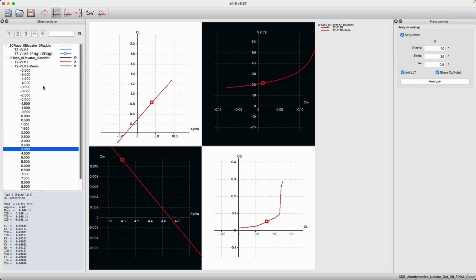And as you increase your angle of attack, the lift coefficient will increase, and because your drag is increasing, the horizontal speed will decrease, right? You can see that from the second graph over here. So right, we'll increase the angle of attack, the airplane will slow down at the same altitude.